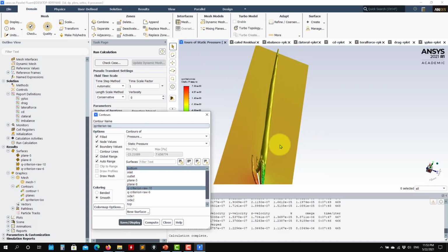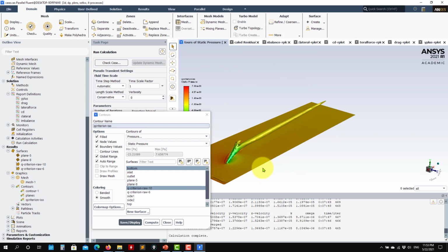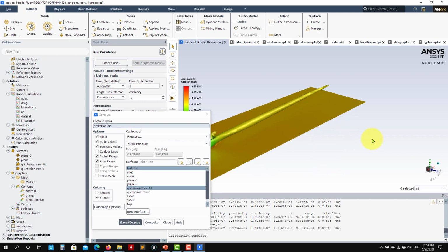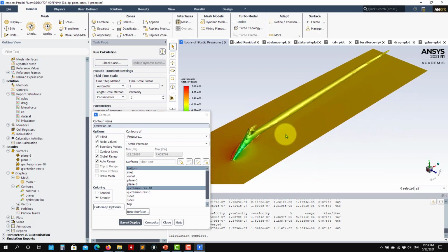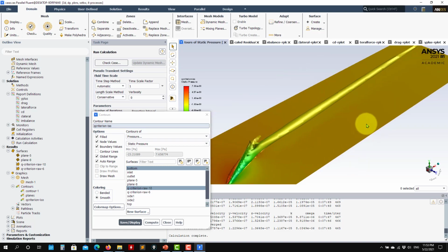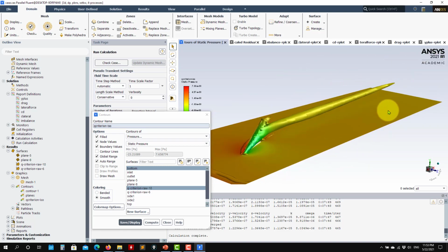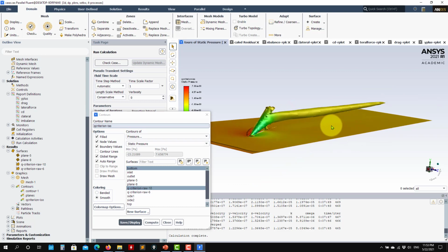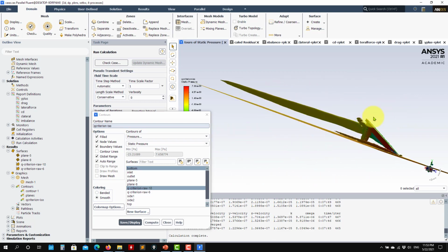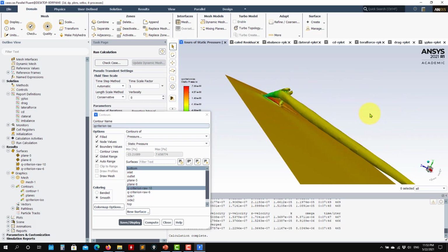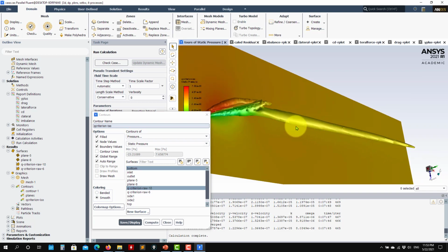I want to add also that curvature correction can be added with geometrical curvature, like in the first case. So for instance, in airfoils, you will find this situation towards the tips of the wings, in 3D wings. Remember that the surface is curved, so this one can also add some dependence in the strain rates and in the spin tensor. So it is desirable also to add this curvature correction if you want to resolve this vortex core very well. In wings, in airplanes, you will find it in the wing tips.